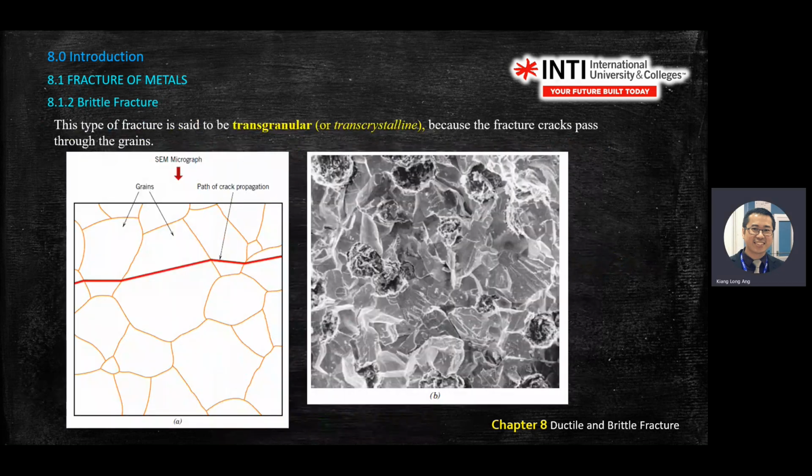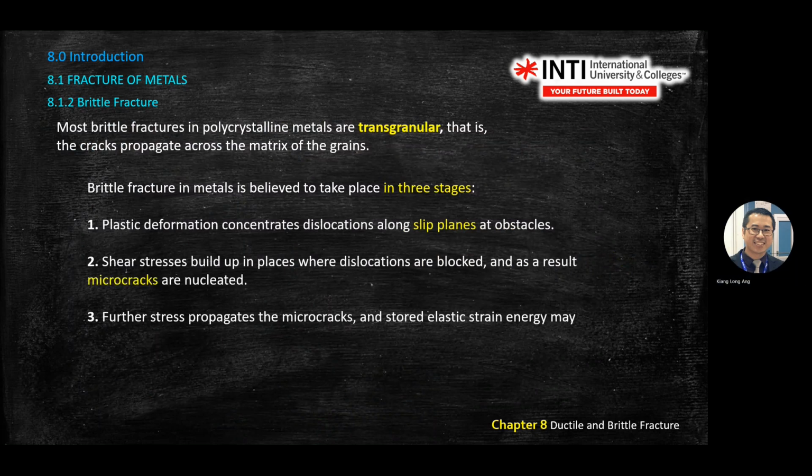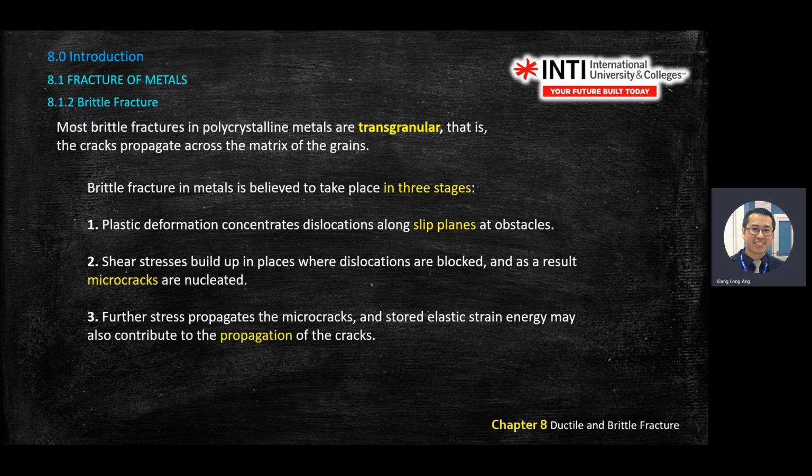Brittle also has stages. Brittle is focused on the slip plane. Also plastic deformation, but the dislocation happens along the slip plane, and the shear stress will build up in the place where the defect happens, and a micro crack starts to form. Okay, so for brittle, the important word is the slip plane.